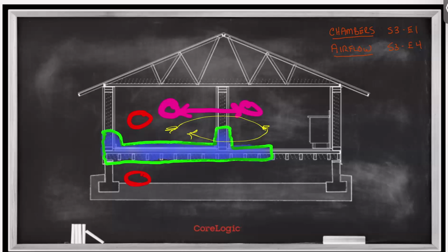And that will be done through circulation of air, right? Through the proper placement of air movement. And this episode up here on airflow gets into a really in-depth discussion on how we do that with air movers and how we establish that circulation. The main principle is that to establish that I do have proper humidity control and a proper chamber established, I measure my psychrometric conditions in one room, my temperature and humidity to be exact, and I measure those conditions in the next room. And if I have appropriate circulation in my chamber, those will match.